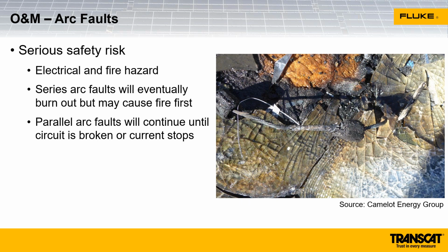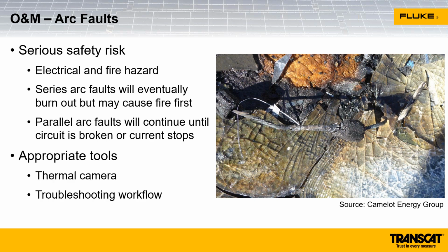Parallel arc faults and series arc faults are going to continue until the circuit is disconnected or they basically burn themselves out. Thermal imaging cameras are really good there. The troubleshooting workflow that I just kind of discussed is another option as well.